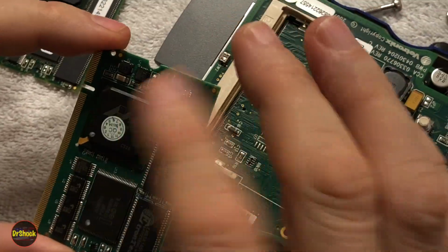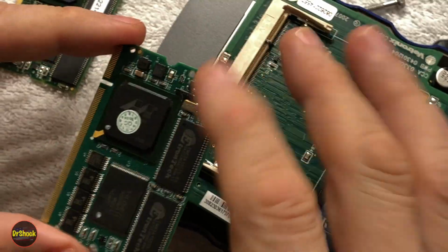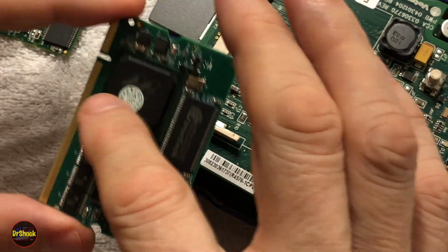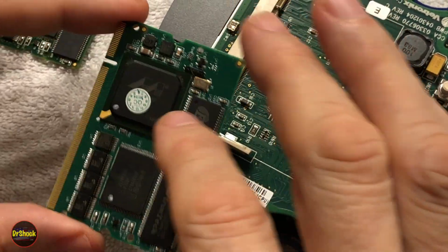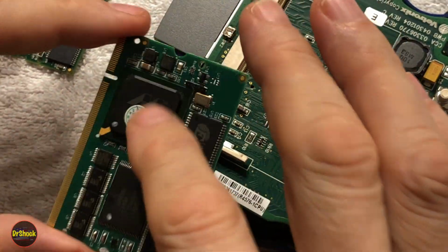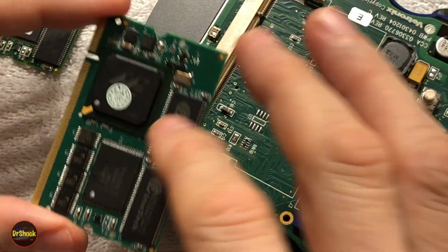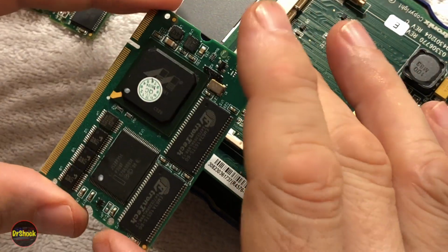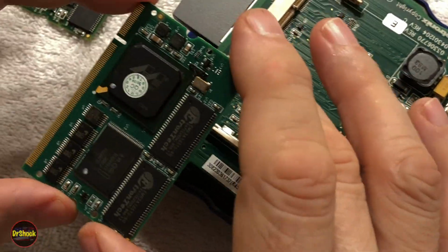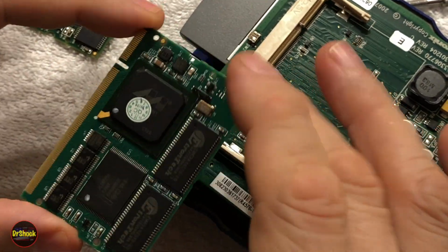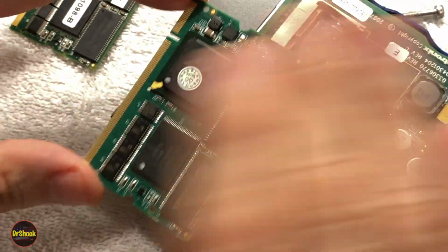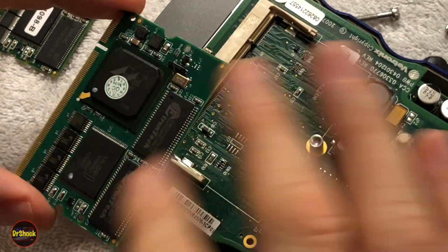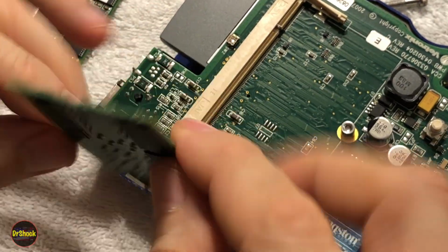If you could source the chip and you had the right equipment, you could then replace it. Or if it was just a case where it's not seated properly, what can happen is there's little tiny solder balls under here, and they can, in some rare situations, become dislodged. And you can reball the chip and replace it. But if the chip is bad, reballing is a waste of time. And even if you did go through the reballing process, if you didn't have the special equipment, this has to be put into an oven and heated at a particular profile in order not to damage this device, and done in such a way that all this other stuff doesn't end up falling off while you heat it up.